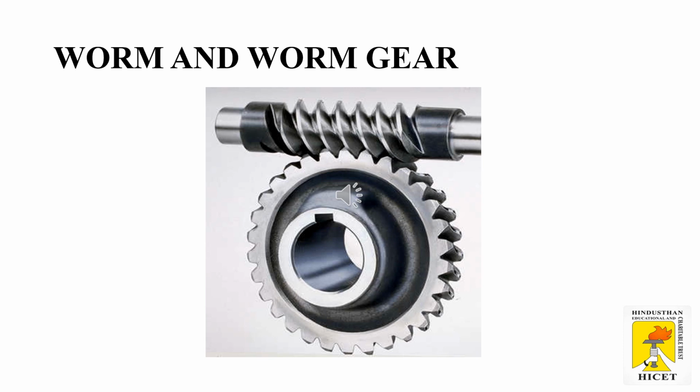Next, non-parallel and non-intersecting axis gears, that is hypoid, worm and worm wheel, and spiral gears. Hypoid gears are used for right angles in which the axes do not intersect. These gears are called hypoid gears because their pitch surfaces are hyperboloids of revolution. They operate more smoothly and quietly than spiral bevel gears.